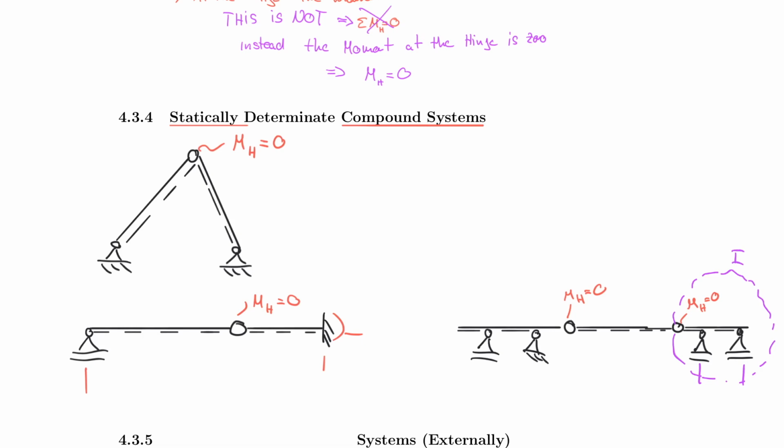But you can also have your equation 2 because you know that your moment there is equal to 0. And in this equation, you have the very same 1, 2 unknowns. And so you have two equations with two unknowns, which you then can solve. And you can find the answer. And once you have those solved, you could, for example, go ahead and take the sum of the moments about this point here and have a third equation.